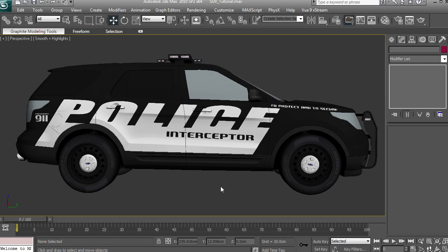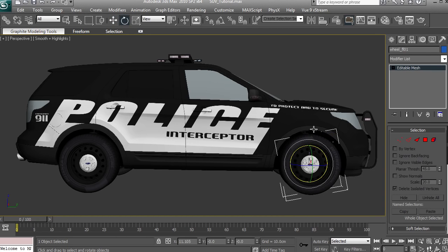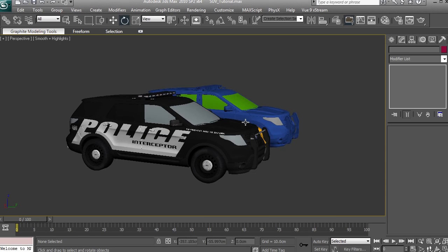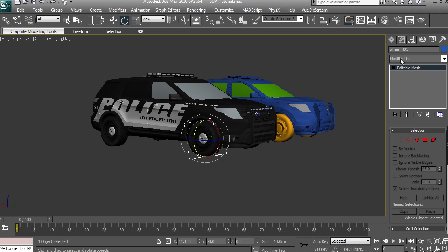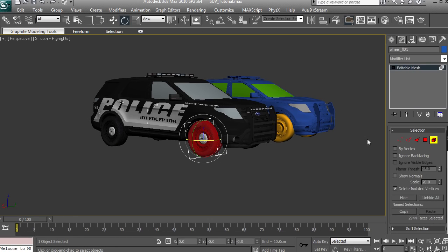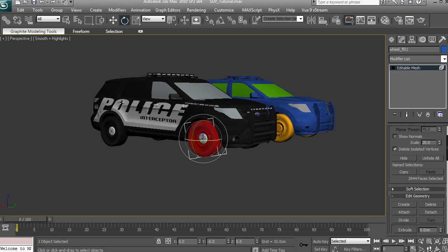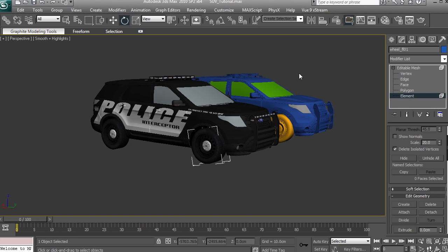Now, we want to be able to have control over the individual objects such as the wheels so that we can make them spin. We also want to be able to have control over the chassis. What we need to do is first separate them by mesh. You can do that usually just by selecting your object, going into the edit mode, and selecting parts of your object and detaching them. I know it works similarly in Cinema 4D. You can disconnect certain parts of your model. You want to make sure to detach all four wheels and the chassis as separate objects.